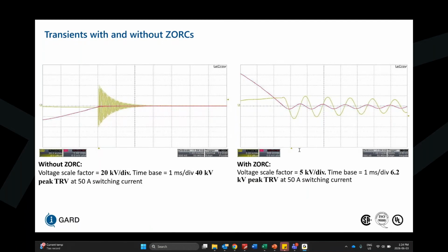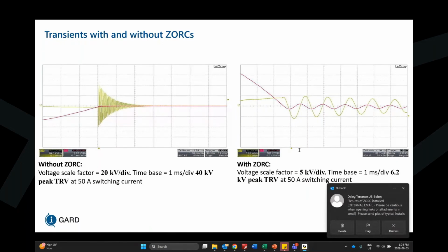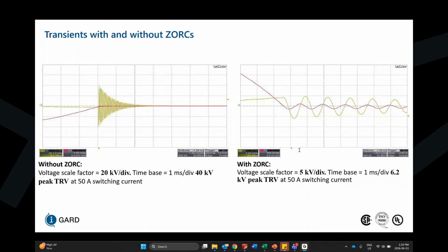That's still a method of switching out a certain amount of capacitance from the system that particular load was contributing to the overall system. So there may be some switching transients of units being switched out of a system as well. In that case, it all comes down to whether you want to take the risk without it or if you want the insurance there, then you would provide something like this. So, case by case basis.